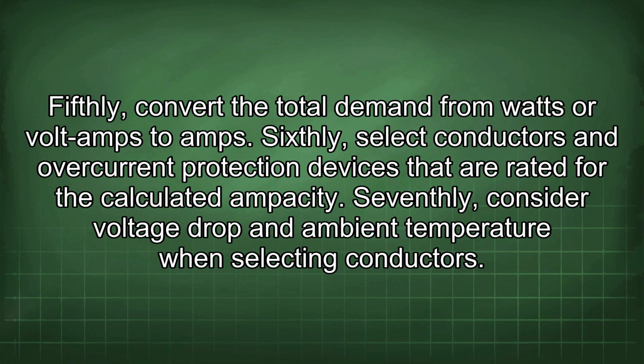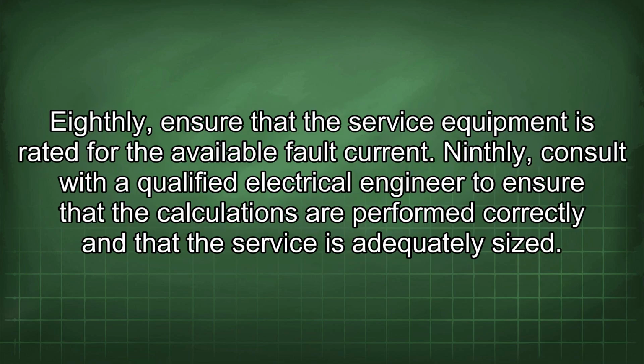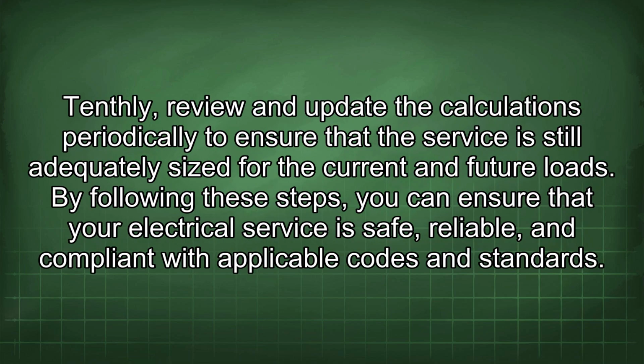Sixthly, select conductors and overcurrent protection devices that are rated for the calculated ampacity. Seventhly, consider voltage drop and ambient temperature when selecting conductors. Eighthly, ensure that the service equipment is rated for the available fault current. Ninthly, consult with a qualified electrical engineer to ensure that the calculations are performed correctly and that the service is adequately sized. Tenthly, review and update the calculations periodically to ensure that the service is still adequately sized for the